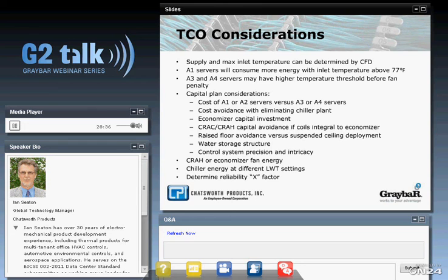And you will find in one example, they looked at a data center in Chicago and actually found a 1% reliability improvement by following Mother Nature, allowing the 90-degree days, but also allowing the lower end of the allowable limit as well.